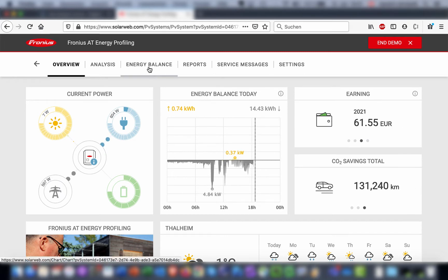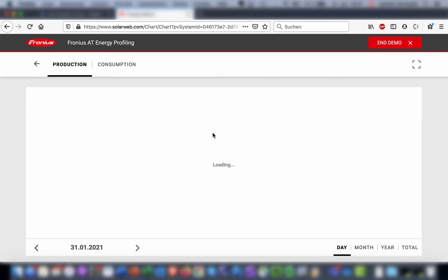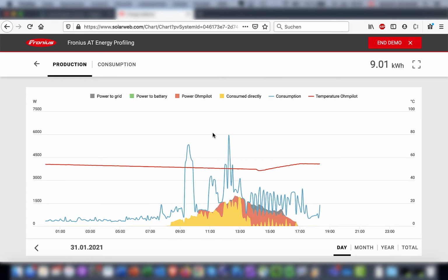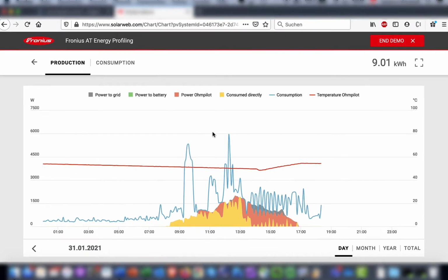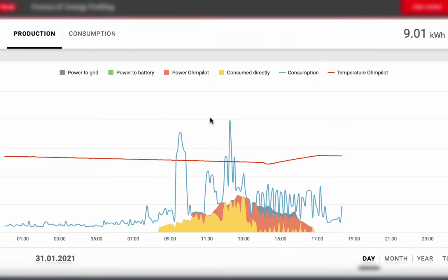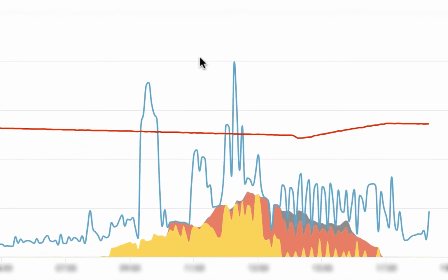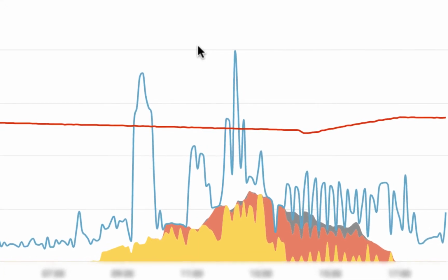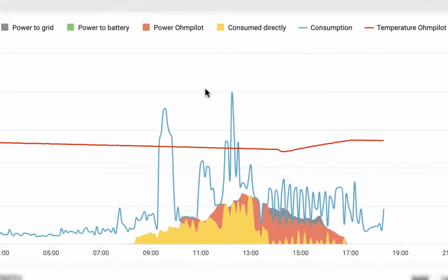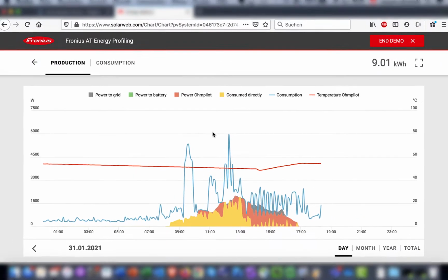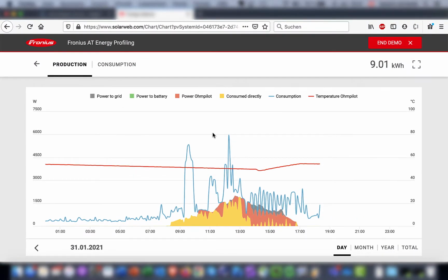Next, we will take a look at how to configure that data manager as to get your local solar production data displayed online, respectively via your SolarWeb app. Let me mention that no historical data of your solar installation is lost, should you be watching this because you need to exchange the data manager. As a matter of fact, the only thing that changes after the reconfiguration is that the new data manager starts handling the communication between inverter and the SolarWeb cloud. That has no effect on data that has already been transferred to SolarWeb before.